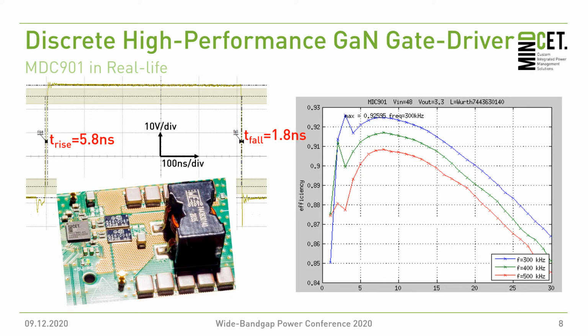This is how the system looks like for real on a PCB. So you see that the power stage, including GaN gate driver, is really compact. For all this functionality, we have one of the most, or let's say the most compact solution in the market. You see that there's only a few external passives needed to accompany the gate driver. This side here is all power stage, an output capacitor and output filter.